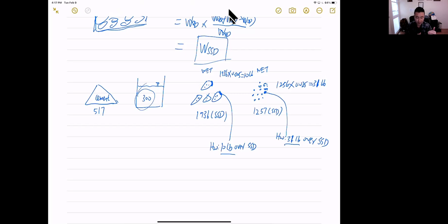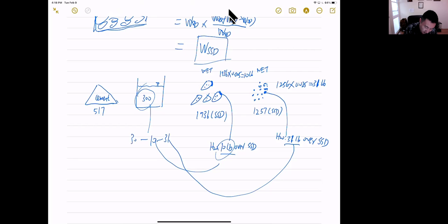So we need to keep the water cement ratio unchanged. The real amount of water we add will be 300 minus the 10 pounds from the gravel, minus the 31 pounds from the sand. So 300 minus 10 minus 31 is 259 pounds of tap water.